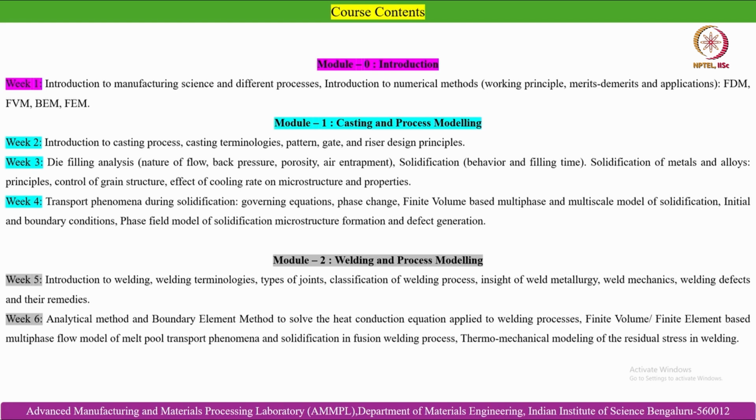Because it is important to develop an appropriate mold to achieve sound cast parts, and that largely depends on the design attributes of the mold cavity, and how to optimize that. For that we will be studying the die filling analysis, where we will discuss the nature of fluid flow, melt flow within the die cavity, effect of back pressure, porosity and air entrapment things. And also we will look at the fundamental aspects of solidification that is taking place during filling of the liquid melt within the die cavity, and also post filling, that means solidification of the component.